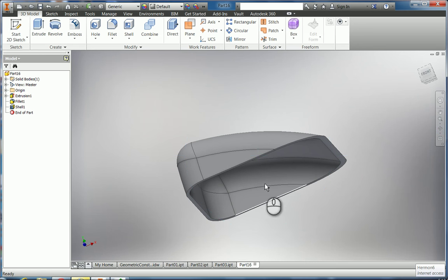All right, next part is a little tricky. We need to put a kind of a connector piece down from inside this that allows this windshield thing to basically hook into the wooden block that we made in the last part. We put these automobile block parts together. Okay, so to do this, I need an offset plane. I'm going to come down here and start an object and extrude it up into the thing, and so I need to offset a work plane.